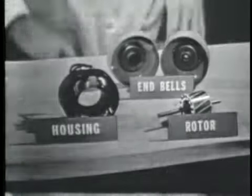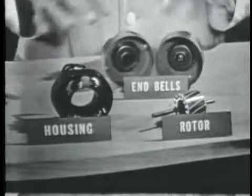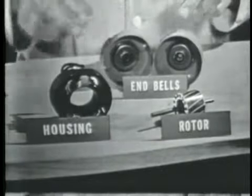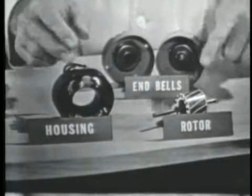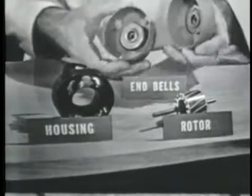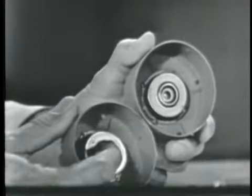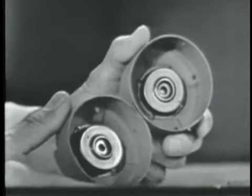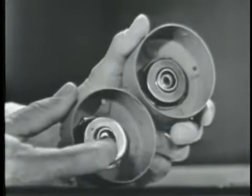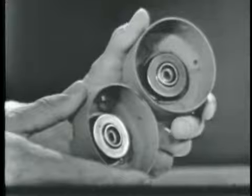Okay. This is a typical induction motor disassembled. Now, as we've said, it's very, very simple. We have the 2 end bells, the stator field windings, and the rotor. Now, let's take a look at these end bells. The end bells are used to house the bearings or the mounting devices that hold the rotor shaft in place. Now, notice there are no brushes or complicated brush holding devices at all. Just simply hold the bearings.